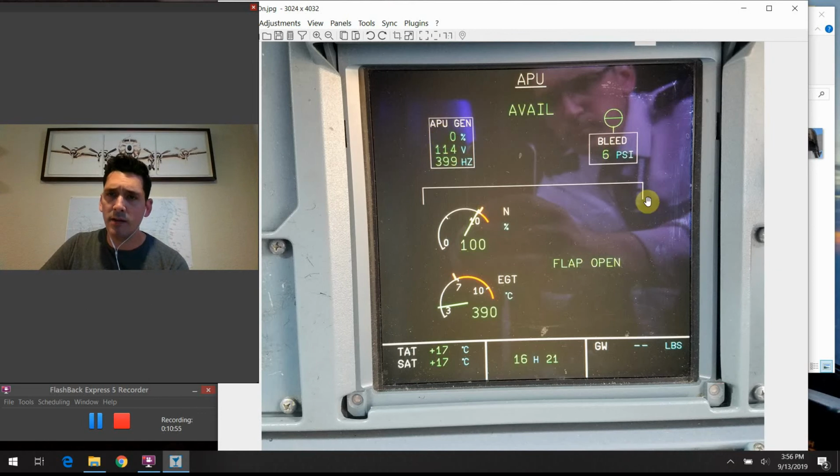Those are the indications on this side. On the right side, you can see by the horizontally situated valve icon that there's no bleed air coming out of the APU and going into the aircraft systems. There's a little bit of residual pressure behind the valve, and that's all it's indicating. So the APU is on in this instance, but not doing anything for us. Pretty simple and straightforward.